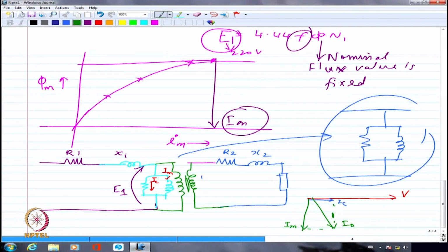definitely to establish the flux. But only because you establish the flux, the core loss is also happening. So if you measure, it will definitely consist of both a real portion as well as a reactive portion. That's why the no load current of the transformer will not lag behind the voltage exactly by 90 degrees. No way. It will definitely lag behind the voltage, maybe by 80 degrees, maybe by 75 degrees, not 90 degrees. This is essentially because the core loss is real. It is happening. You can't negate it, right?